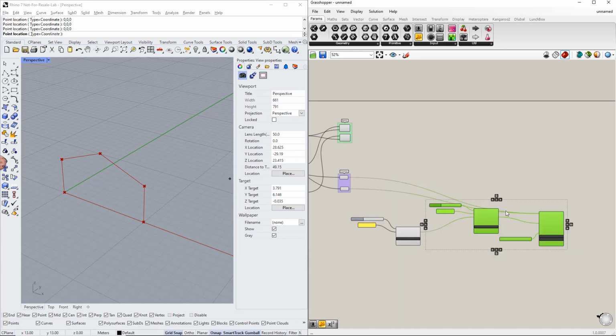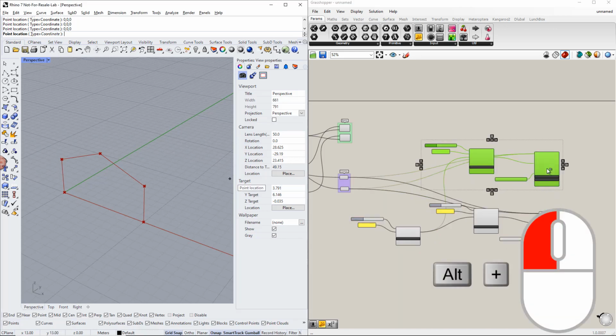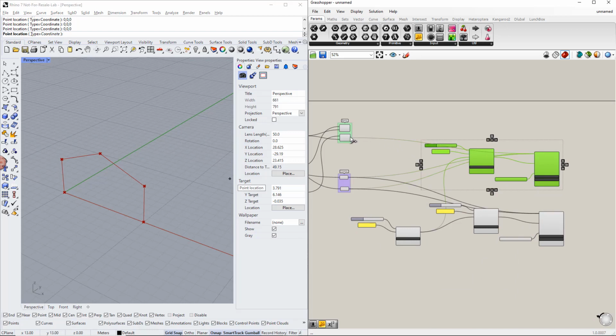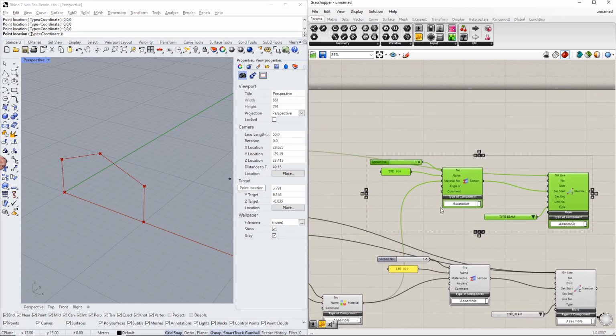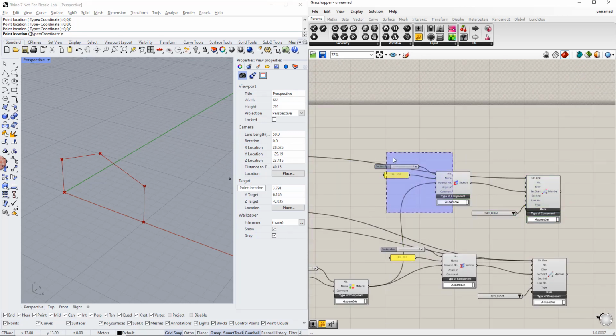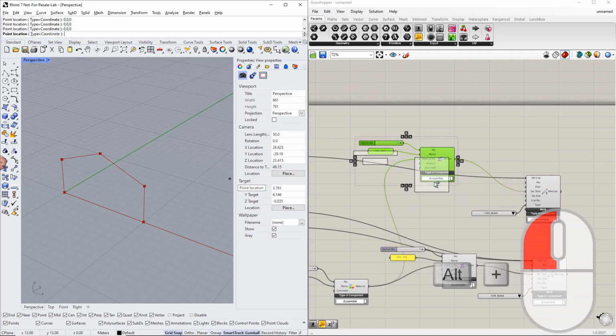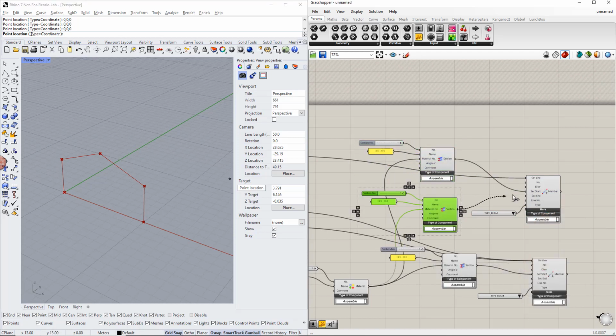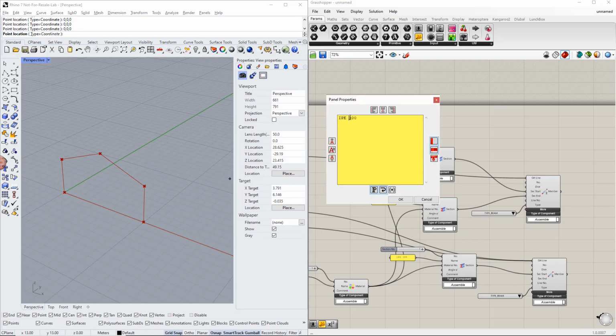For the beams, we repeat the same procedure for every individual member, because we will assign a cross-section at the member start and the member end. We will change the cross-section to IPE 500 at the member start.